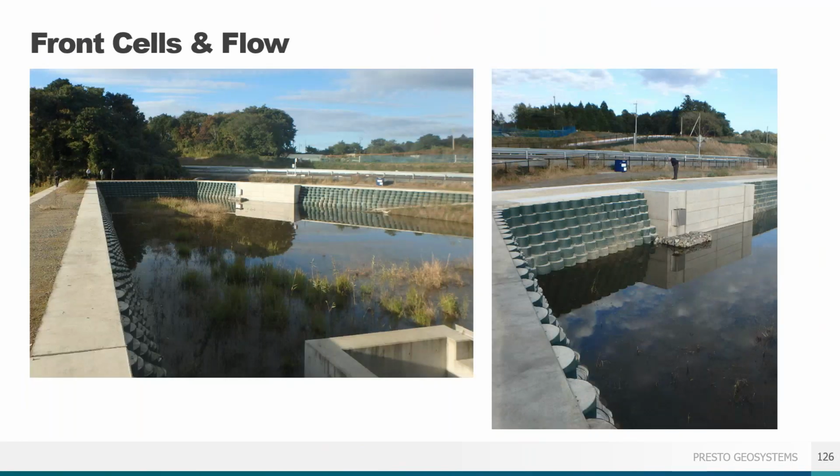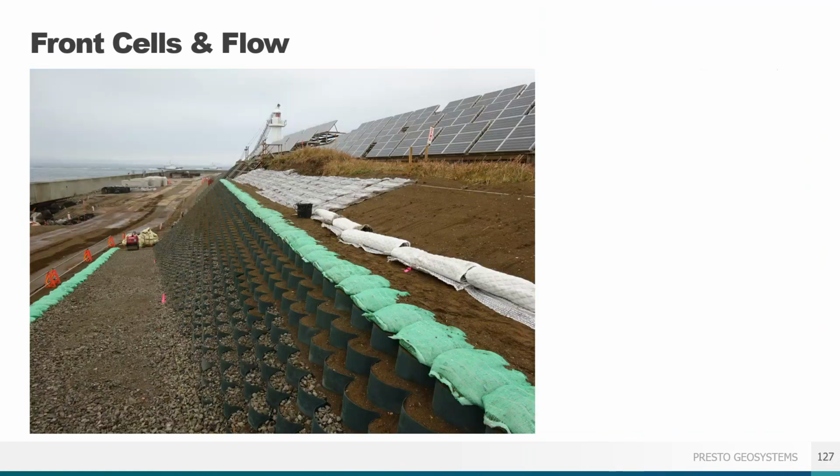We mentioned the drainable fill a few slides back. You may also consider grouting the front cells or filling them with concrete when high flow is expected, like in this highway retention pond. Or use a mix of medium, as you see in this project, with aggregate fascia along the pathway and topsoil for vegetation elsewhere.